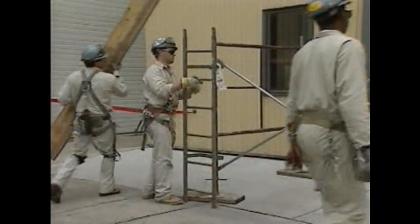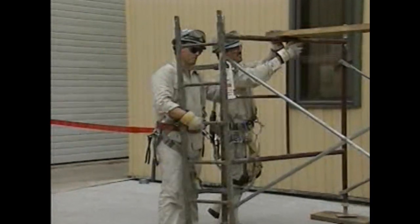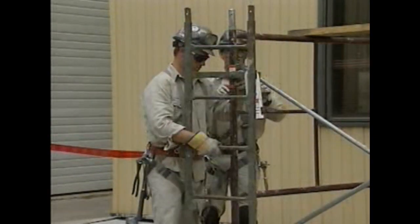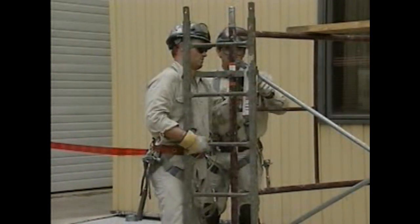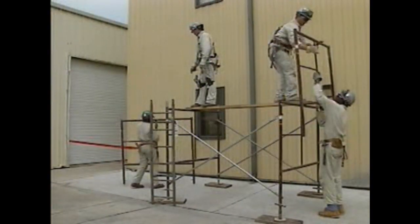The first section of the scaffold ladder is then put in place, and a scaffold plank is laid across the tops of the end frames so that the builders can assemble the next level. The assembly procedure is basically repeated at this point.